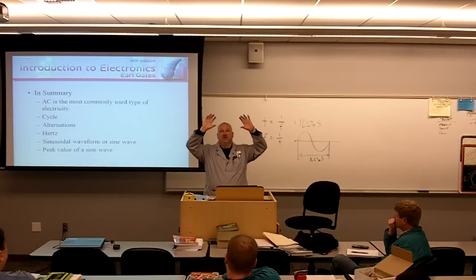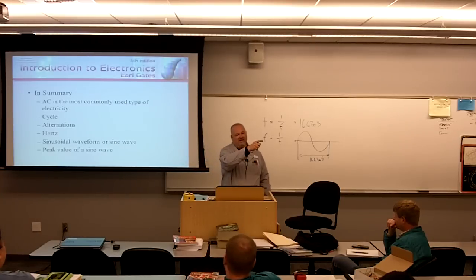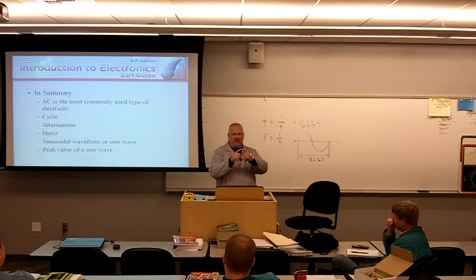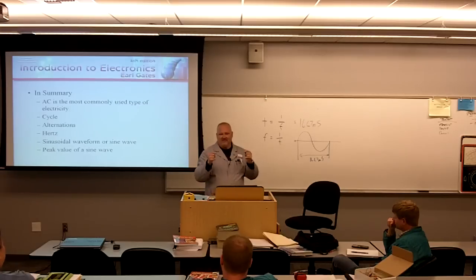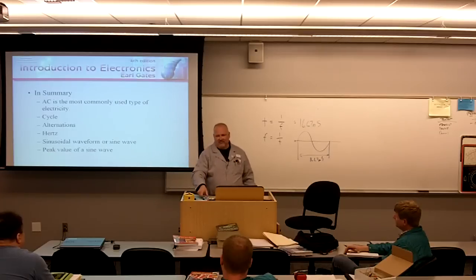One of the things I had was an oscilloscope set up with a function generator. If I questioned the computer, I would take that signal and route it to the oscilloscope, just like we have here in the lab. Then I'd get a function generator, just like what we have in the lab, and feed the input into the function generator, out of the function generator into the oscilloscope, into what's known as my x-axis. So my y-axis is the unknown frequency. The x-axis is my known frequency. And I could mix those 2 signals together on the face of my oscilloscope.